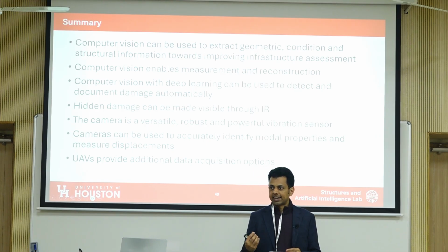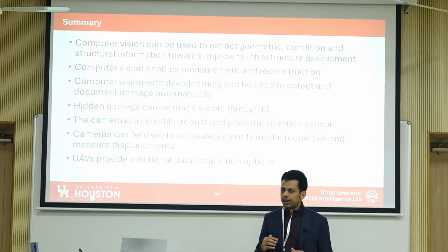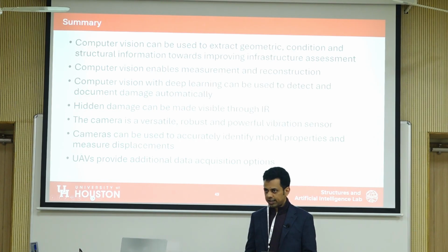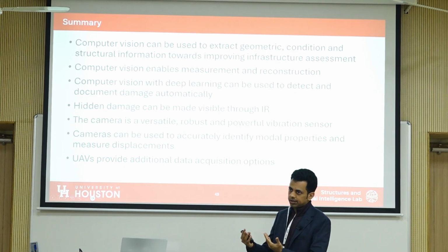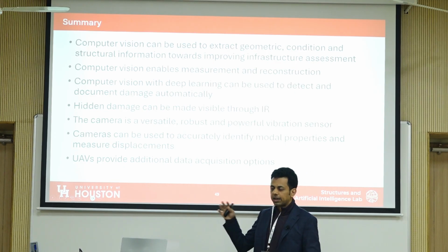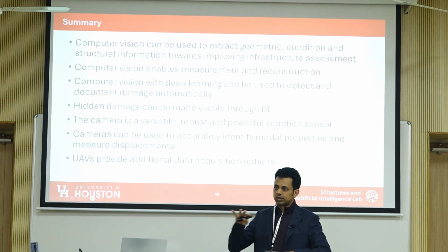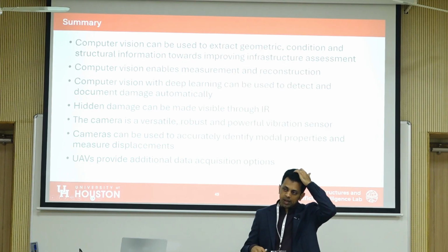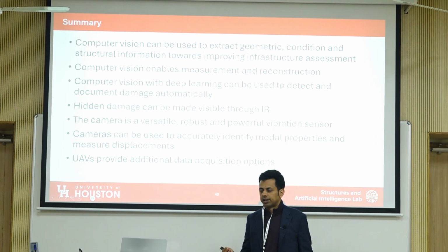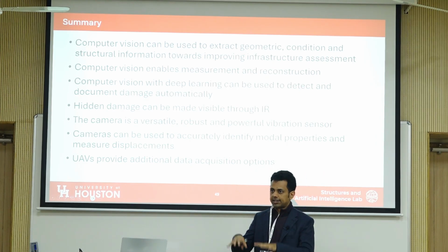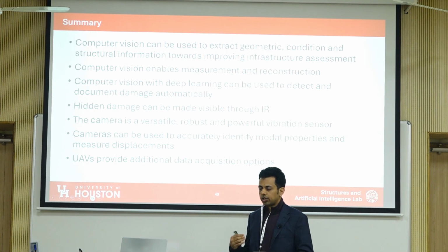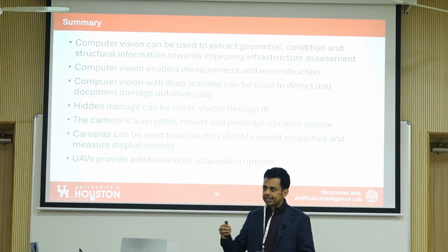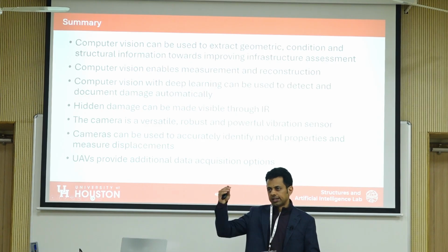Also for things like identifying cracks, if there's very high dynamic range, which means there's very bright and very dark areas in a picture, it becomes difficult for the camera to adjust to that. So you may have to use HDR, high dynamic range, which accounts for those changes in intensity and normalizes, so that you can see things even in the darker portion or the lighter portion.